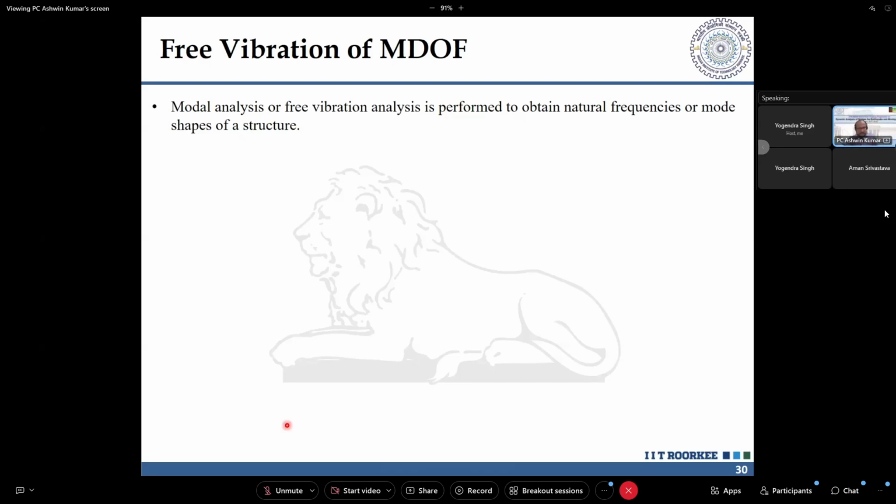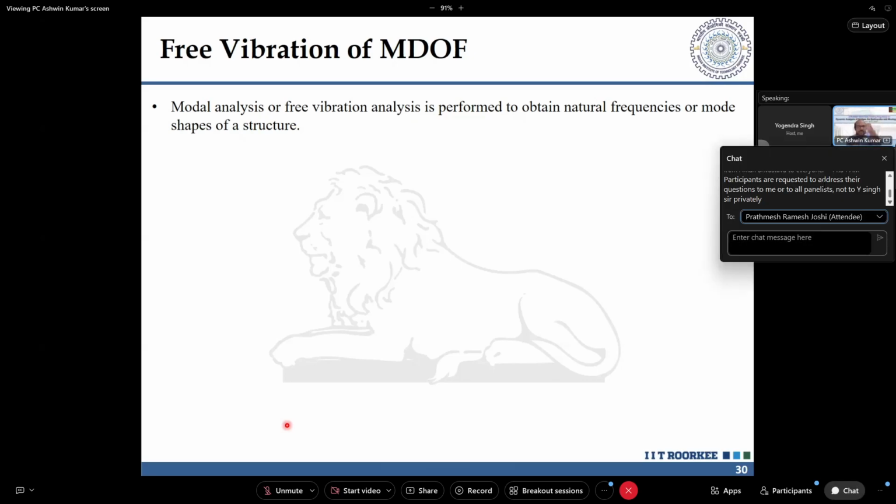The moment it started vibrating at nearly 4 hertz, you saw that the most fundamental frequency of the system was activated, where each mass was moving in phase. If the lower mass was moving towards the right, the middle mass was also moving towards the right, and the top mass was also moving towards the right. Everything is in phase and moving in tandem, in sync, left to right.